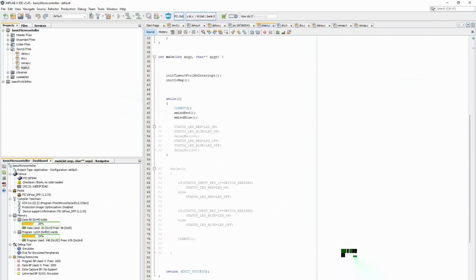So till now, what we were doing was we wrote the code in PIC16F84. We selected this processor because this was the only processor which we were able to simulate in the Proteus free version. But the issue with this is it only has 68 bytes of RAM and 1 kilobyte of program space. So with this space we cannot write much code, and basically we will not be able to write the display driver. So one, you have to figure out a way to get a Proteus full version. Only after that will we be able to proceed with this.